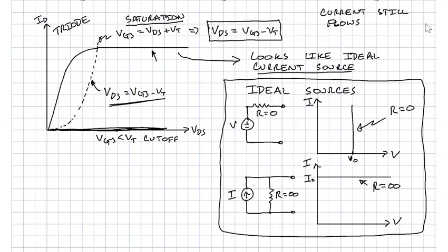Okay, so what we're going to end up doing is we're going to break this up. It's most useful to use a MOSFET in either one of these distinct regions, either solidly in the triode region or solidly in the saturation region, where they basically operate near ideally in terms of looking more like a resistor, or looking more like a current source. So we'll show you in a minute a model that unifies this full ID VDS characteristic. I guess what I can add to this is, let's maybe add one more curve, and let's add a couple more.